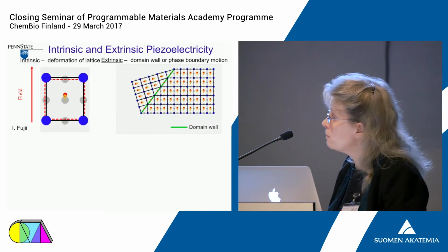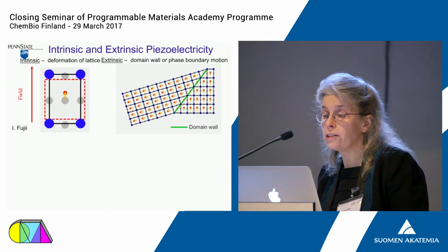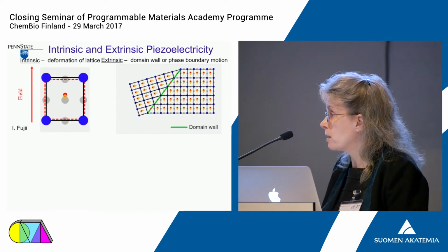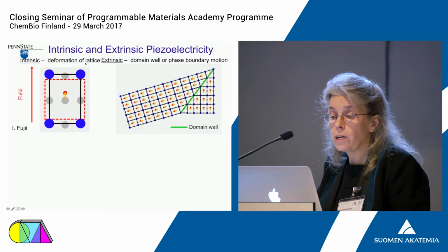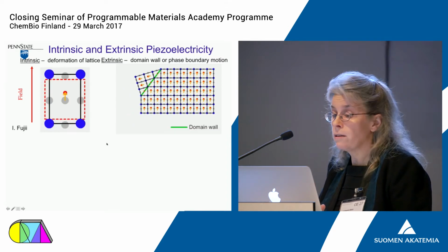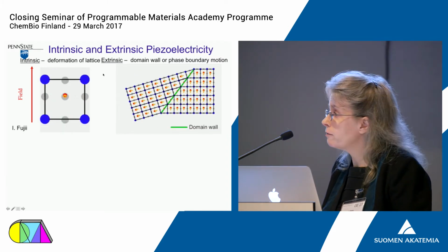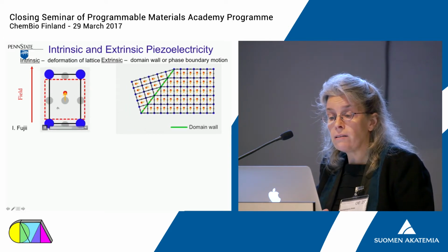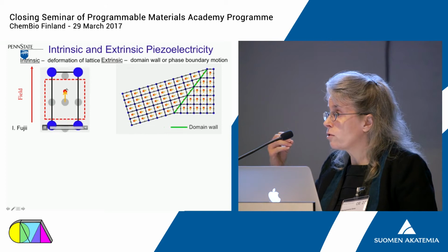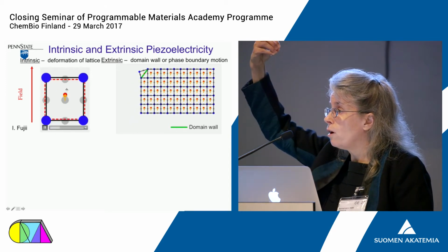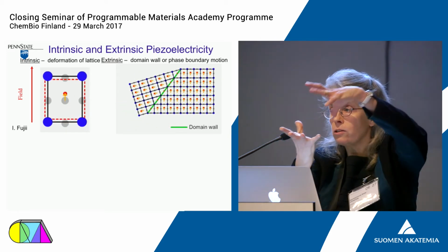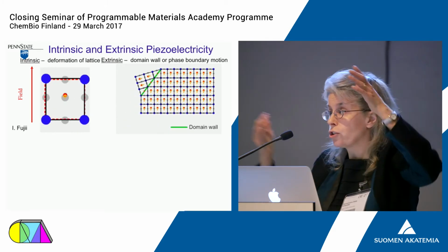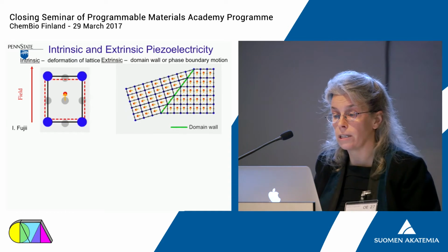And so if we look at these materials and try and imagine why do they show this electromechanical coupling, I've shown the two primary mechanisms here. The first is what I will call the intrinsic response, where you can see as we apply an electric field that's parallel to the polarization direction, we displace that atom that should have been at the center of the unit cell progressively further off the unit cell, and as it does so, the unit cell continues to elongate parallel to the polarization direction, and it contracts laterally.